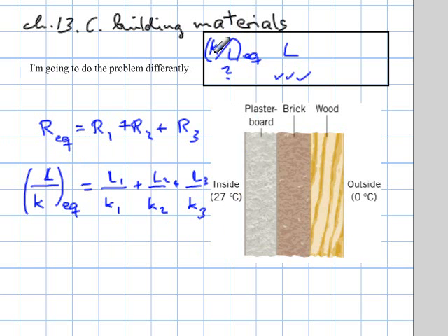And that means that the conductivity for each of these here is given as such in the book. So for the first one, it's 0.3 joules per second meters Celsius degrees, 0.6 for this one, and 0.1 for this one here. Now, when we put them behind each other, we figure out that the insulation has increased, and that means that the conductivity has to go down. So whatever the result is here for the heat conductivity should become less, because that's the idea behind it.